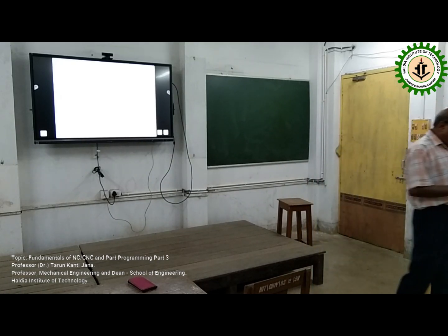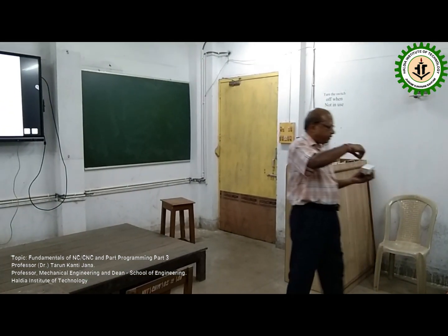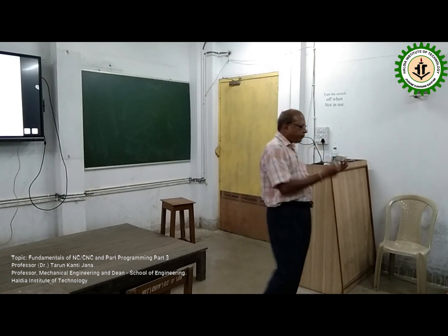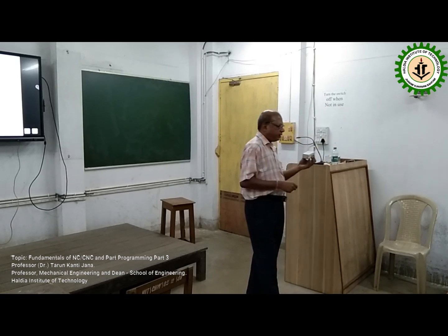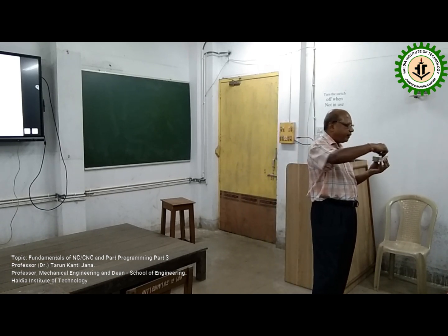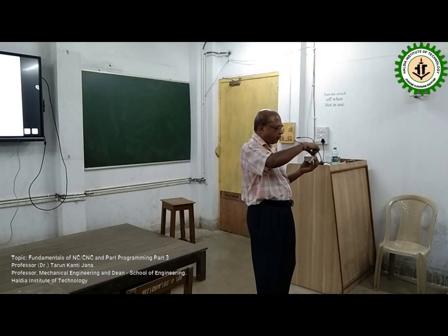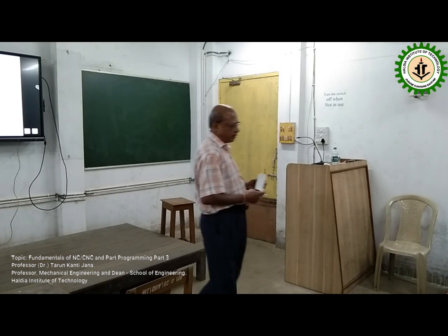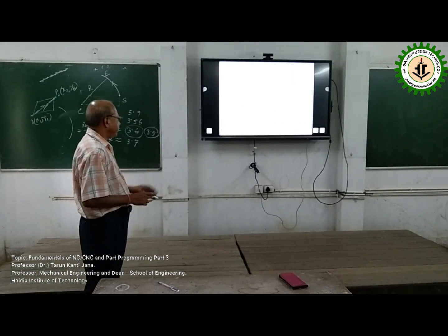Now why is it required? From a mechanical perspective, suppose I want to cut all of these four sides, so this is a cutting tool, it keeps on rotating this way and moving this way. Now quite often it happens in the corner that some small chips or burrs adhere even after movement. So in that case, what is recommended is that, having rotational motion, don't give any further linear or feed movement. So hold that particular position for a few seconds. In that case there will be lagging, so burrs will be eliminated. So if that is the intention, you can use G04. Otherwise, it is not required.